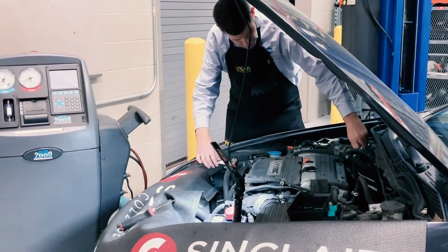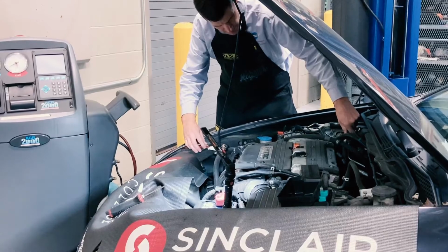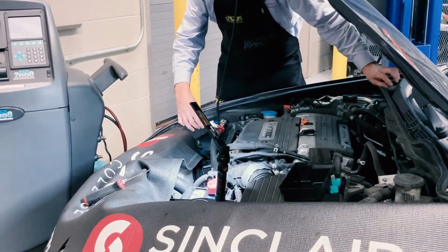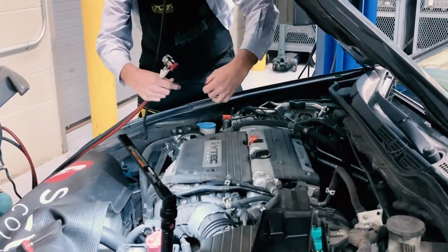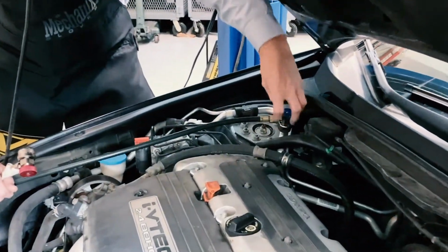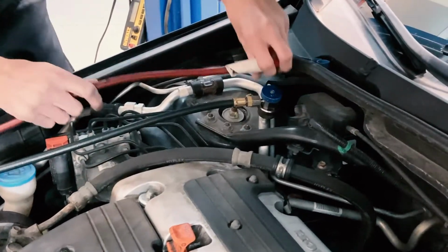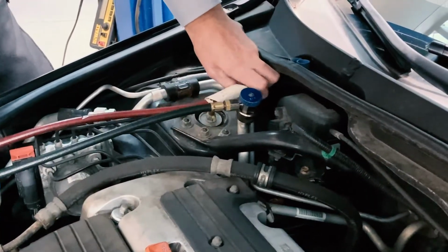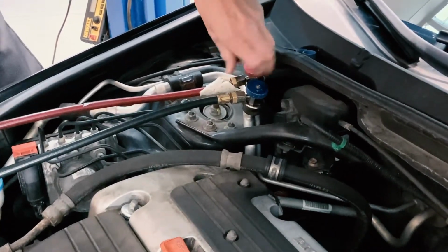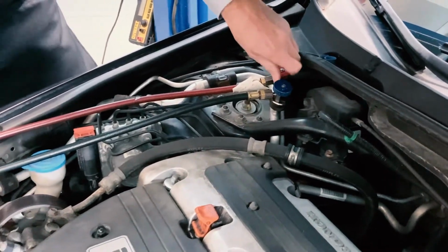And so our smaller port is going to be... and you can hear a little bit of a hiss there. It's probably some residual refrigerant. And we're going to go ahead and connect our low side gauge, smaller port. This is an R134A system. We're going to connect our high side service port. Make sure to get that coupler on there. There we go. Run it down to access the refrigerant pressure. So now we'll be able to see this on our mechanical gauges on our machine.